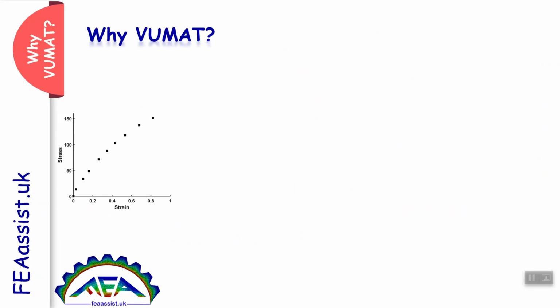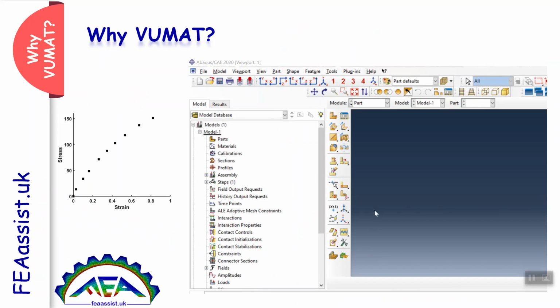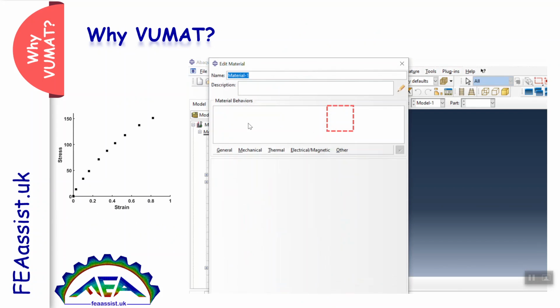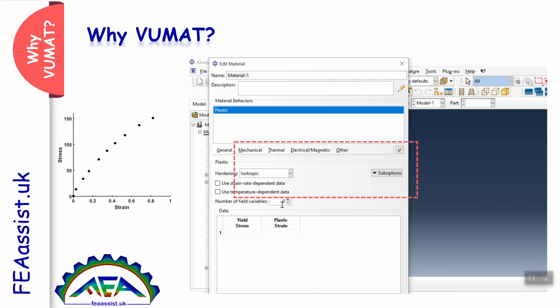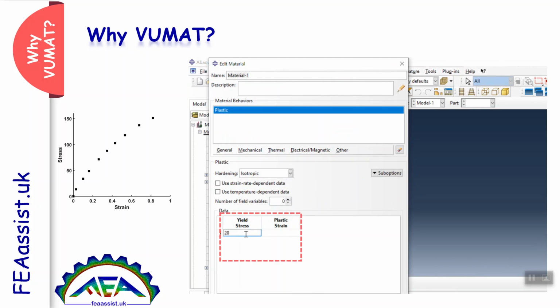The first strategy is that you have some of the points of your stress-strain or load displacement curve from the lab or published experimental results. Then you can easily go to the Abaqus property module, define a new material, go to the plastic behavior and enter those points like this.